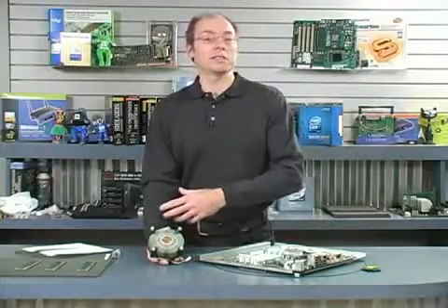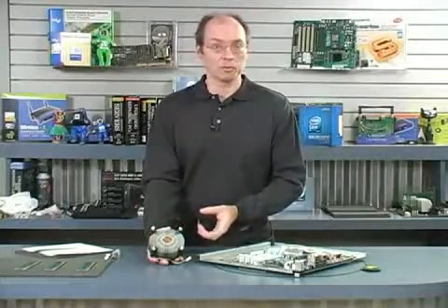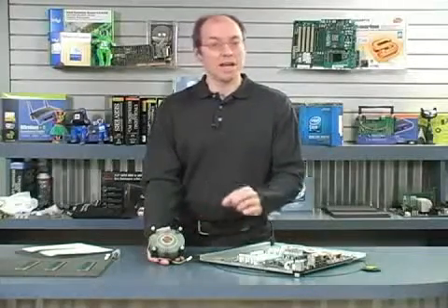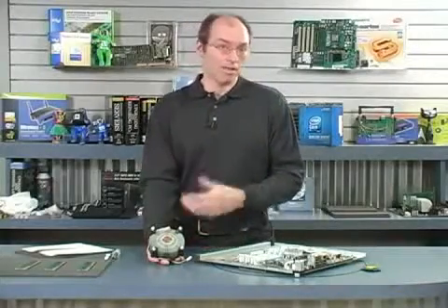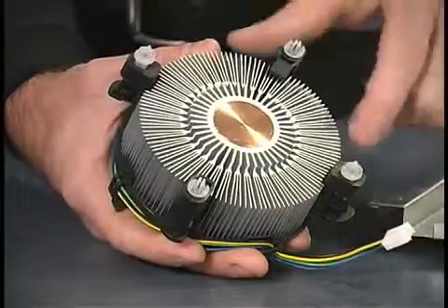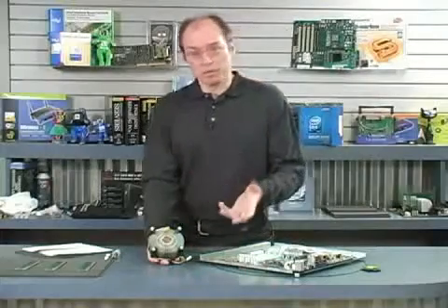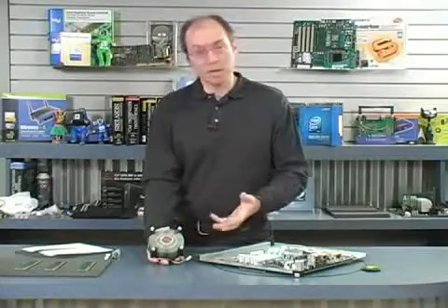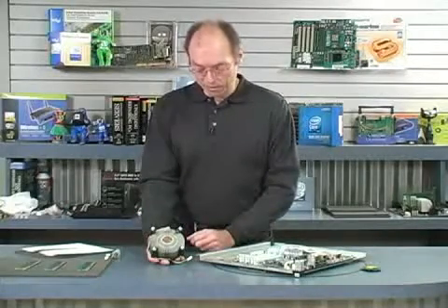So why don't we see heat sinks that are all copper? Well, the problem is copper is expensive. It's a lot more expensive than aluminum. It has twice the thermal conductivity of aluminum, but it also costs from 3 to 9 times more, depending upon whether you're going by weight or volume. So the compromise is that many heat sink manufacturers will have a copper core, like you see on this one, and then surround it with fins made out of aluminum. Depending upon the performance nature of the heatsink, some heatsinks might be all aluminum, or some might be all copper. In any case, those are the different types of metals that you'll see.